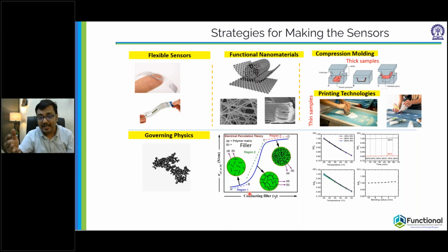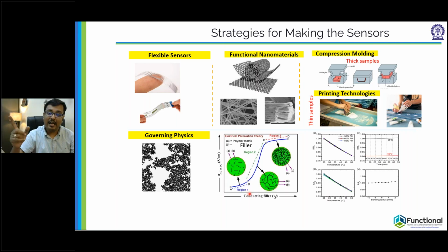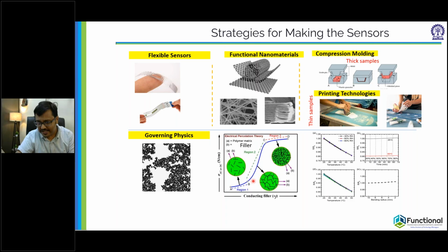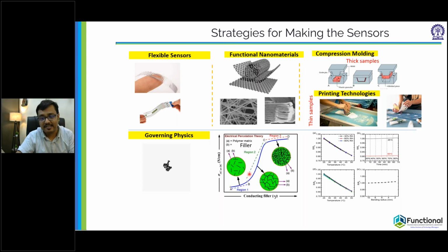So what you are going to get is a delta R factor. Now this delta R is the resistance at time t under the influence of any external stimuli minus the resistance R0, which is measured under undisturbed condition. So this is what gives you the relative resistance value, or the delta R by R0 value. That gives you an idea about how much disturbance is created, and this is how resistive type rubber sensors typically work.